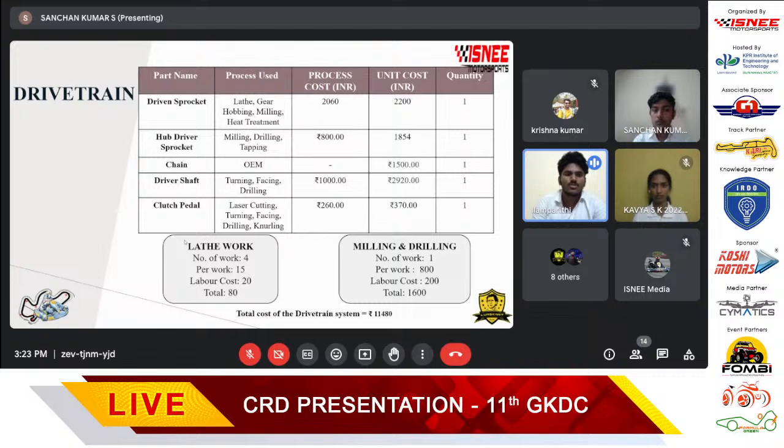Clutch pedal. In the clutch pedal, the process uses laser cutting, turning, facing, drilling, and knurling. The throttle pedal and clutch pedal are the same model we designed. For the main part of the pedal we used laser cutting, and the driver foot pressing area we lathed, with knurling, facing, and drilling. The process cost is 260 rupees. Unit cost 370 rupees. The total cost for the driven train system is 11,480 rupees.